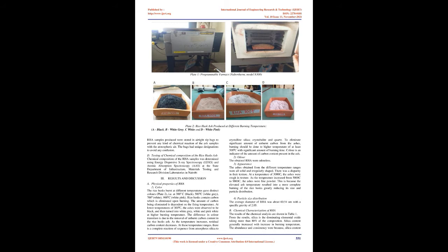Thermal treatment of the specimen was carried out in a laboratory programmable furnace, Nabertherm model N300. The electrical connection was three-phase with a maximum heating temperature of 1300 C. The chamber kiln was heated from 5 sides and a special arrangement of the heating elements ensured optimal temperature uniformity. Heating elements on support tubes ensured free heat radiation. The programmable furnace was self-aerating with semi-automatic air inlet flaps for optimum ventilation of the kiln.